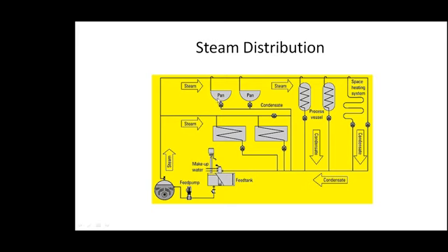Here what we see is a steam trap, one of the most important components in steam applications, because when you don't have a steam trap, what will happen? There will be a lot of loss of steam. Steam will keep going along with the condensate, and then the condensation will not be proper. So it will take more time for the process to heat up. And if the trap is not there or if it is not working, the steam leaks. So there is a waste of steam.